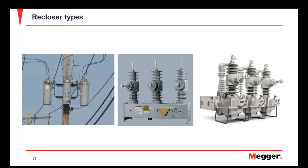And the reason that we want these reclosers to be able to operate independently is because if there is a permanent fault where one of the single phase reclosers becomes locked out, you still have the ability to maintain 2/3 of that load, or 2/3 of the circuit that it's meant to power.